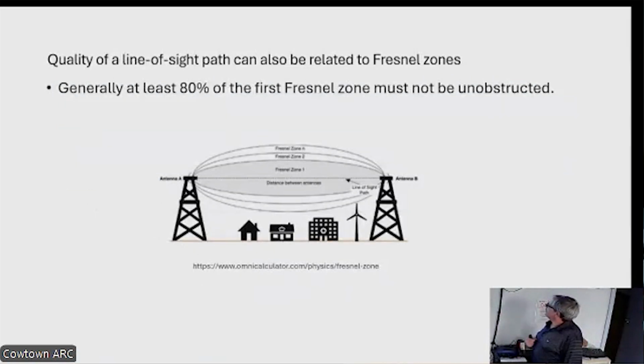This idea of Fresnel zones also applies if you're trying to do a line of sight transmission. Nowadays we don't see so many point-to-point microwave links, because of the internet, fiber optics, and spacecraft communication. But one of the planning aspects of these systems involves the obstacles in between the two antennas, and how likely the wave is to interact significantly with those obstacles. Again, we define that in terms of Fresnel zones.